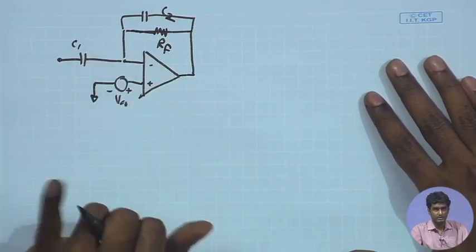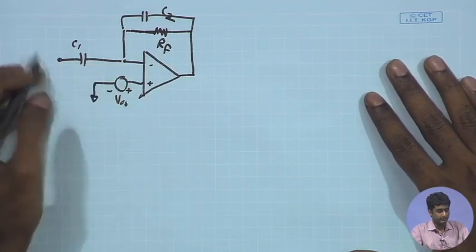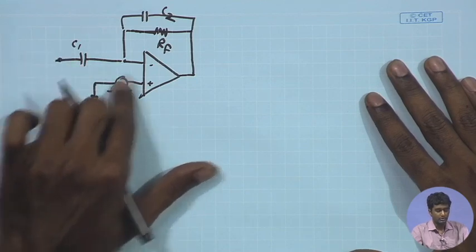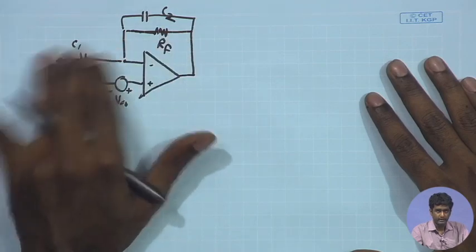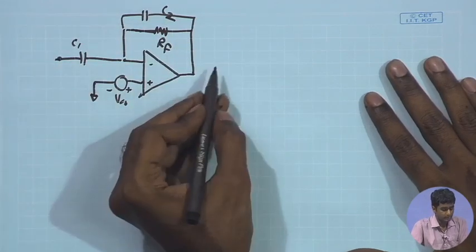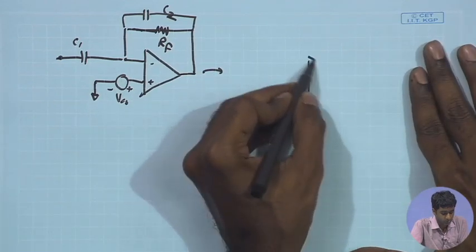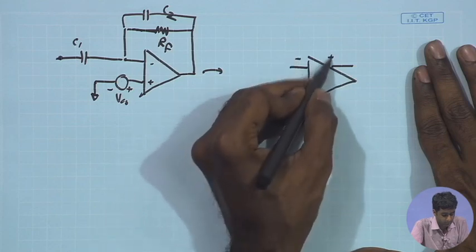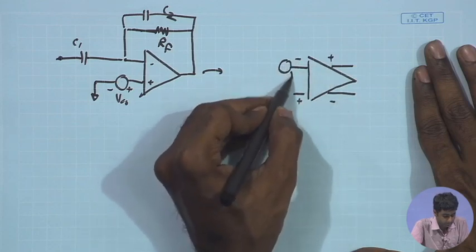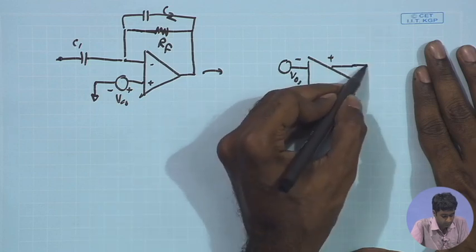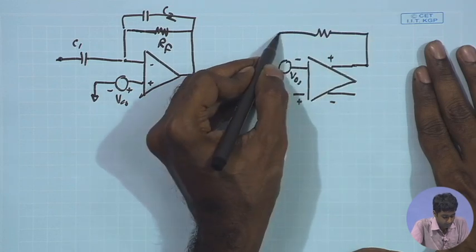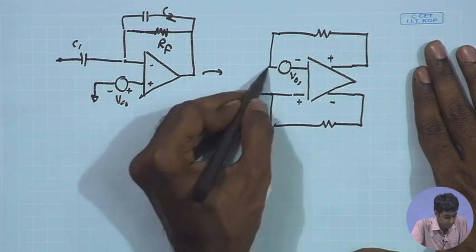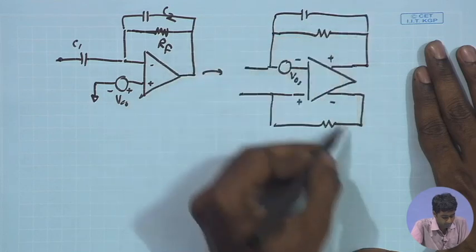Of course, I am looking at single-ended version, and if I try to see what is the effect of this particular offset on the output in presence of the RF and C1 and C2, or we can correspondingly look at the fully differential version also and try to see that if there is an offset, what is the effect on the fully differential output. We can keep the offset at any point, and then you have the corresponding capacitive feedback.